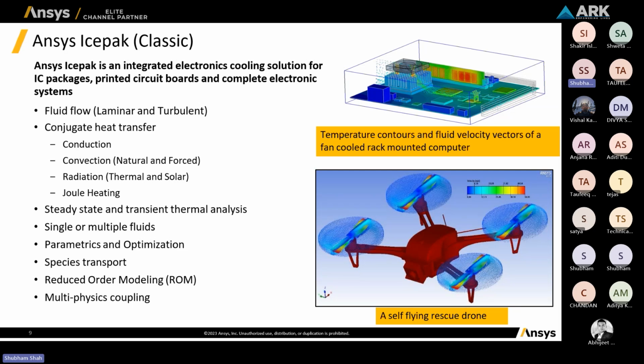So it will show you the last of the results of the 2000 iterations when your flow is steady. So it won't give you the intermediate results. If your focus is time dependent, like how the flow is behaving with respect to, let's say, 0.5 seconds, 1 second, 1.5 seconds, 2 seconds, and you want to see the behavior with respect to your time intervals, then we need to perform the simulation in the transient analysis.